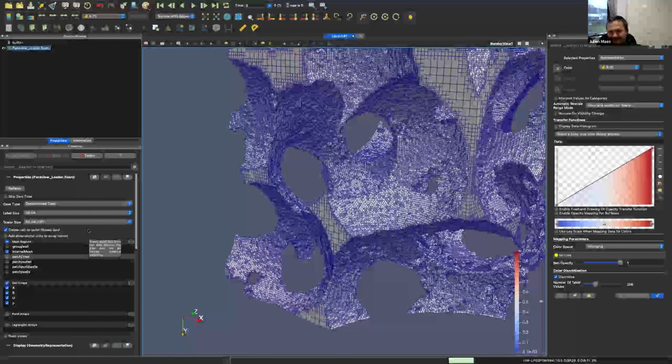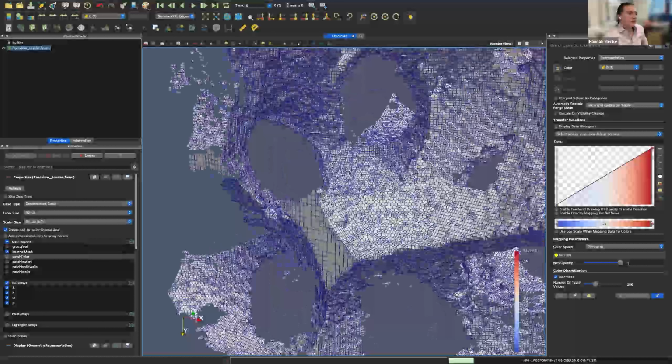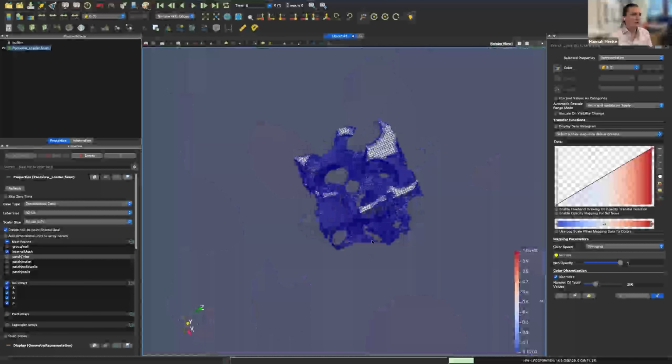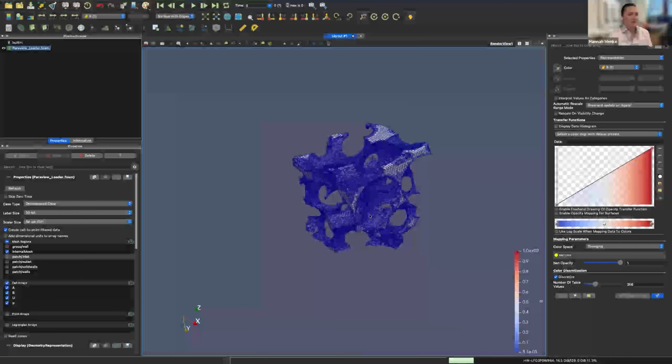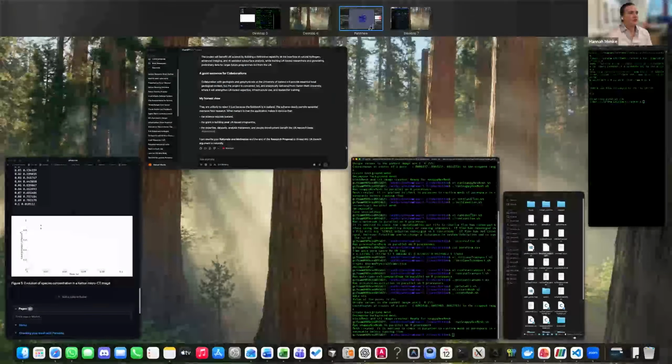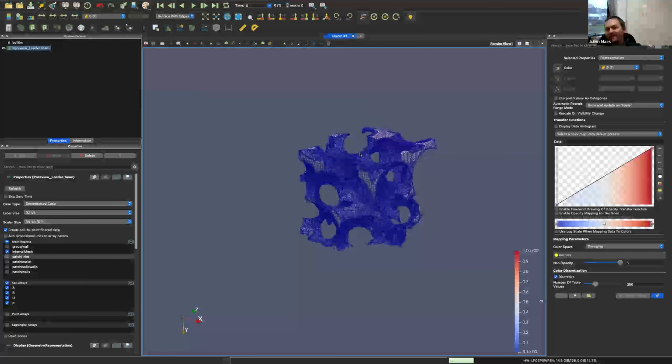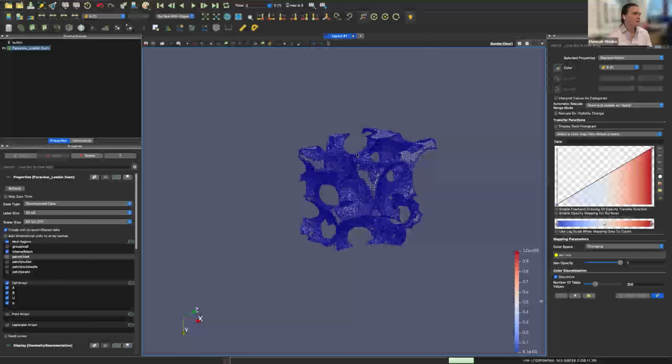Is that the new mesh? Yep. So this is a new mesh, and you can see we've got really big blocks, medium-sized blocks, and little blocks this time because we did refinement level 2. But of course, the whole domain is smaller. How long did that take? Did you ever record? I think it was slightly longer the first time actually, because the domain's a bit smaller.